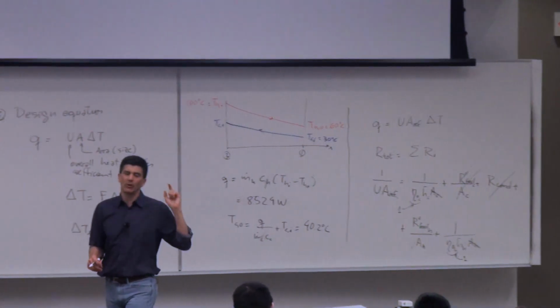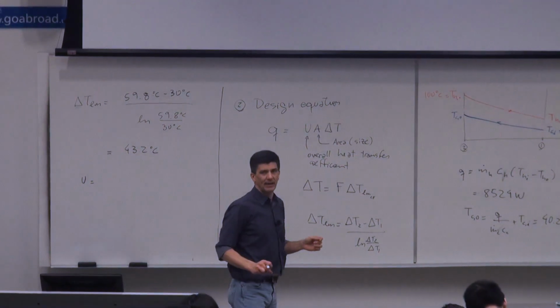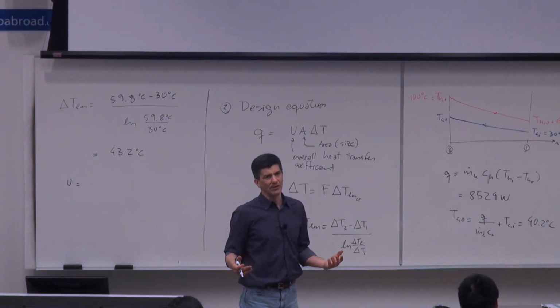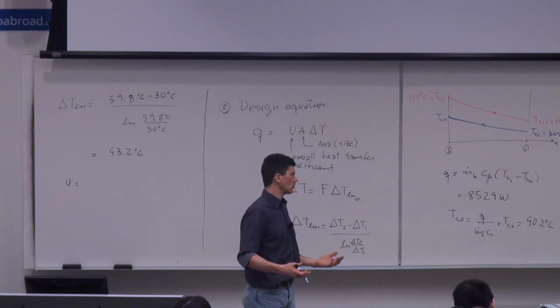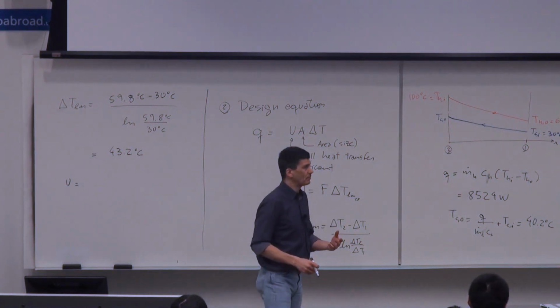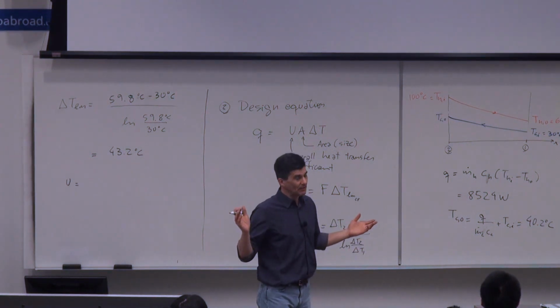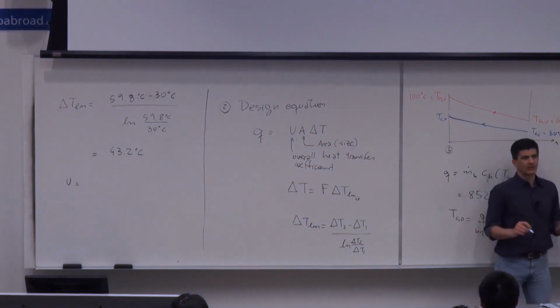This is true because we're saying it's a thin wall pipe. And we say it's a thin wall pipe because they didn't tell us anything else. Right? But in any case, when you design a heat exchanger, what you don't want is to be creating your own worst enemy, that is thermal resistance. So you design it with as thin a pipe wall as you can. Now, you have everything you need to calculate this overall heat transfer coefficient.